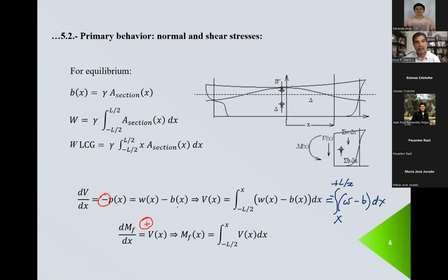Okay, that's the procedure. We're following the second procedure that we presented. Remember, the first one is to do a full dynamic response of the ship in waves, which is very long. The second one is this one, in which we impose an equivalent wave, and we assume a quasi-static equilibrium. And the third one, which is very simple, is just to apply the formulation from the Classification Society. I'm going to present it with just a couple of comments in a few seconds.